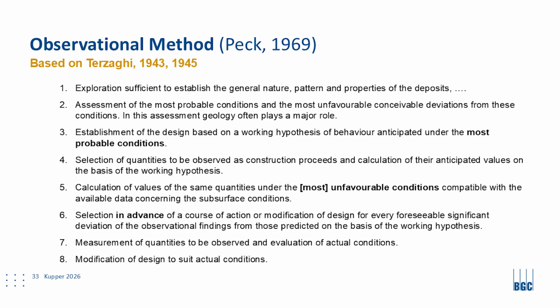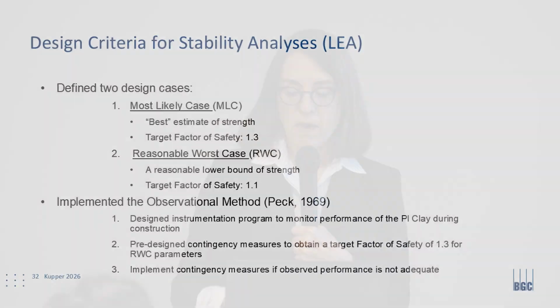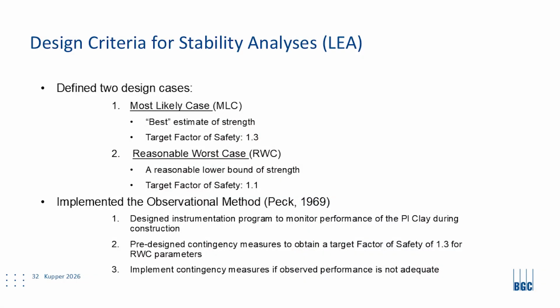So these days, performance-based design is the cool thing to do. I think it's cool too, but it's being said as you either use the observational method or performance-based design. Not at all. You manage risk and uncertainties to develop a robust design by using the observational method, and then you could use either limit equilibrium analysis or deformation analysis, with the difference that the design criterion is a certain factor of safety, which unfortunately you can't measure in the field, so you need proxies or other things to decide whether you are in one design case or the other.